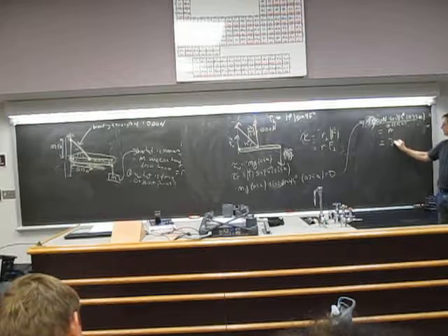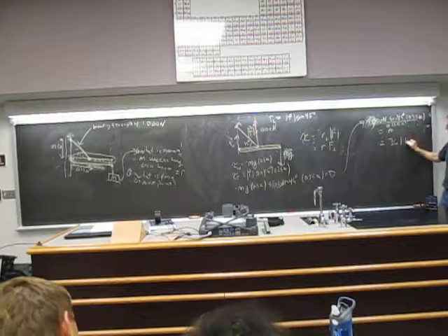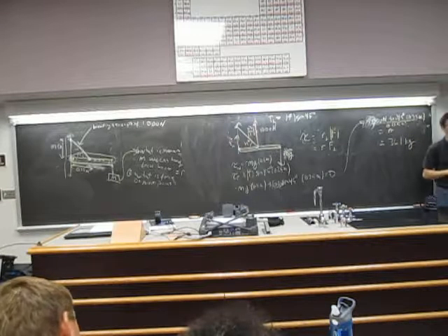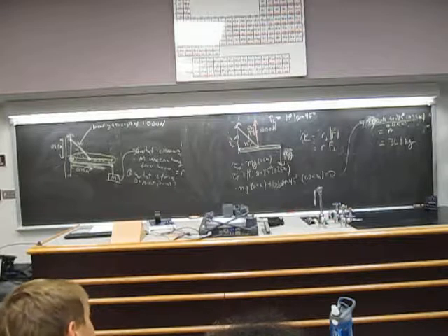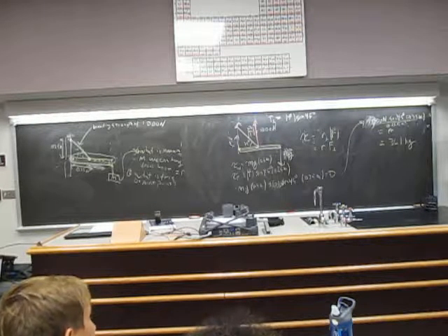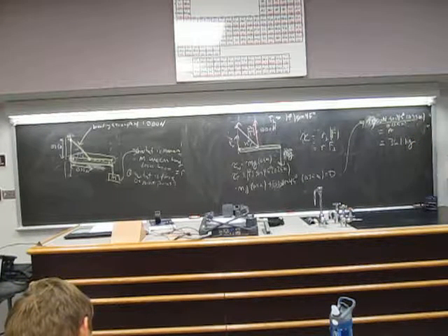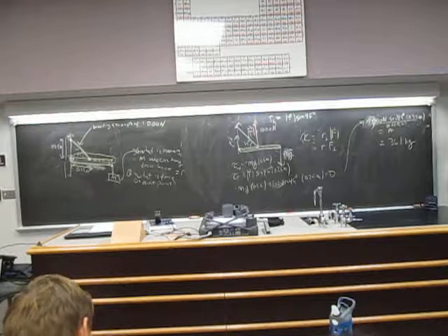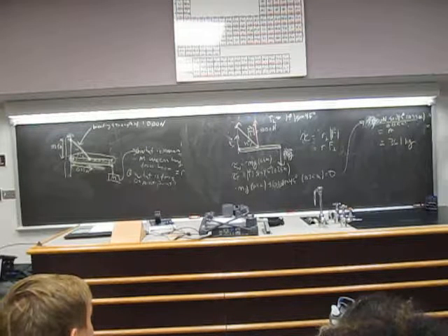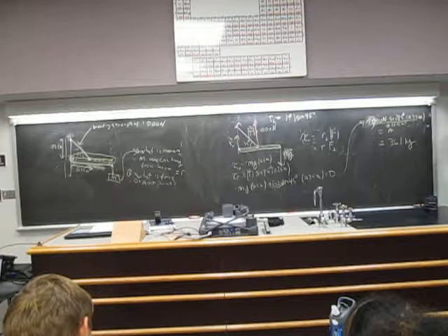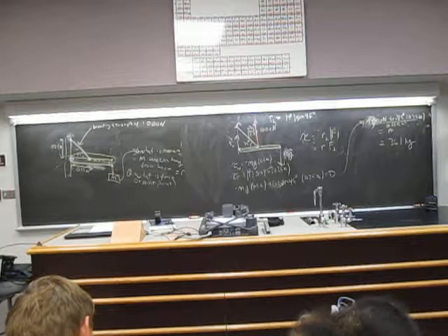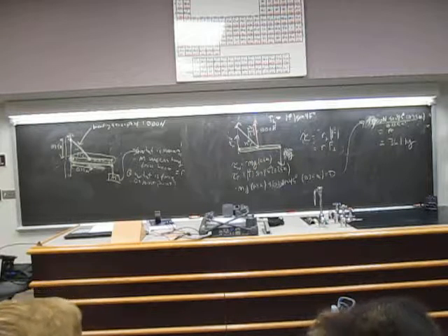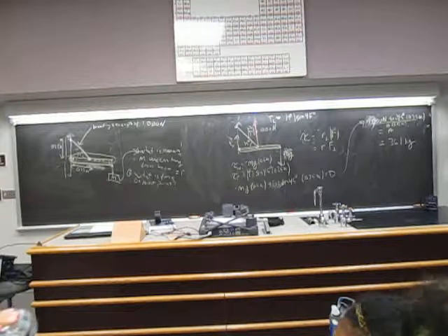So m is 36.1 kilograms. Makes sense? That'd be the maximum mass that you can safely hang there without having that thing break. It'd be useful in practice, if you know what the breaking point of your boom is, you can now figure that out.